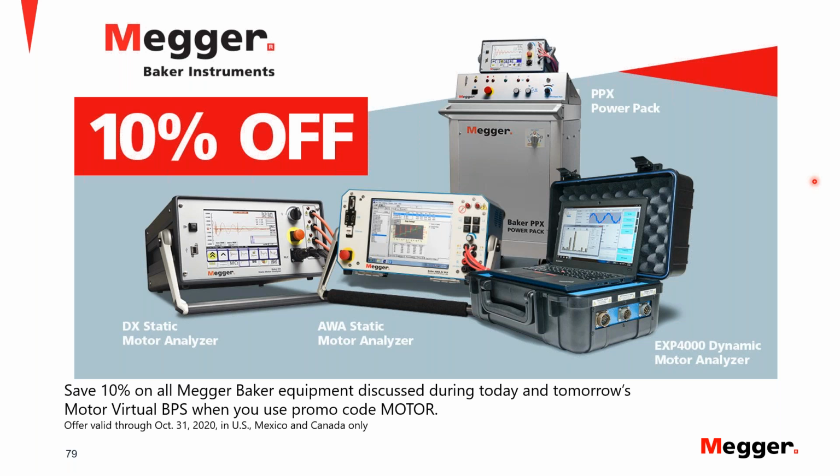It's any 10 degrees rise that affects the insulation, the life of that insulation. So 80 degrees Celsius may be okay for that motor if it's in an ambient temperature that the motor was designed for. However, if my ambient temperature is at 60 degrees C, then I may be overheating that motor just because it starts out so high. So in that case, you'd want to pick a motor that had a 60 degree ambient temperature rating on it. So hopefully that answers the question there.